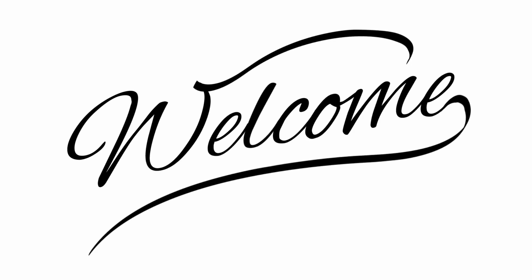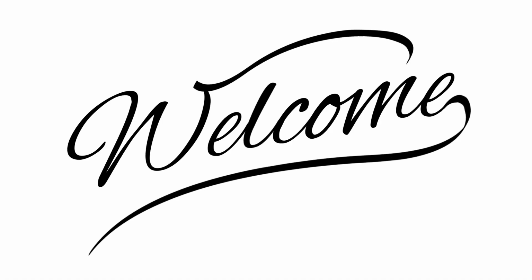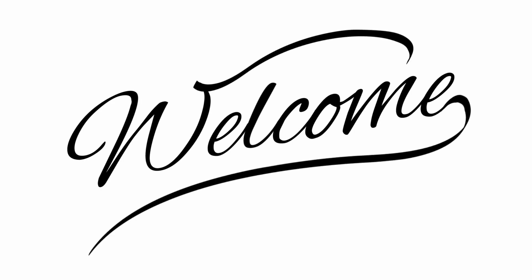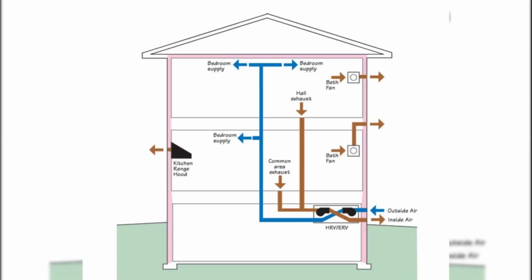It is clear that as homes get tighter and better insulated, the old rules of HVAC design don't apply anymore. Loads drop dramatically, but comfort becomes harder to get right. So what's the number one rule of HVAC design in these homes? The most critical principle for low-load HVAC design success is keep velocity up and mix to ensure proper air distribution